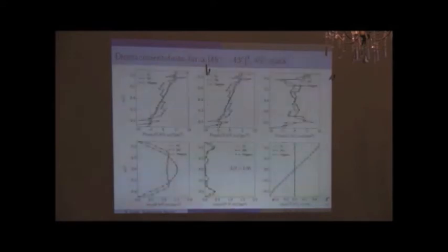All right. So I do the same presentation with a more complicated stack. It's a 9-layer, still symmetric. You see that we have complicated distributions, and this is why you have such a large literature about laminated plate theories, because of capturing those effects. Everybody noticed that the exact solution is very, very complicated, and we need large enrichment of plate theories, plate theories with many enrichments. And this is the same for the transverse shear stress.